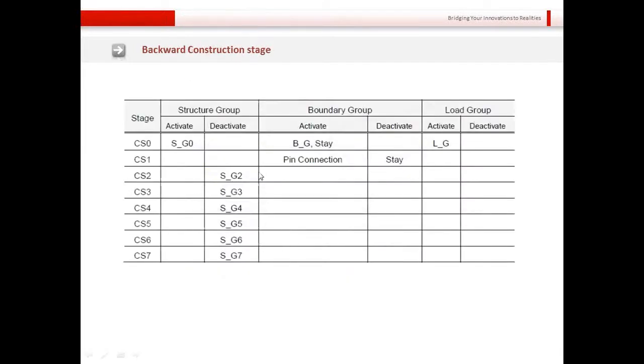So this is how our construction schedule looks. First stage, we'll activate the complete structure, all the boundaries and the stay conditions, and we'll activate the self-weight load group that we have defined.